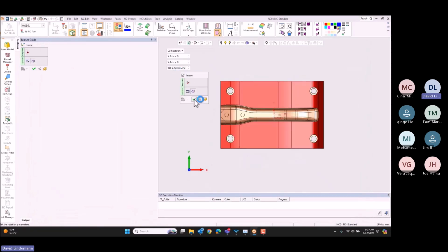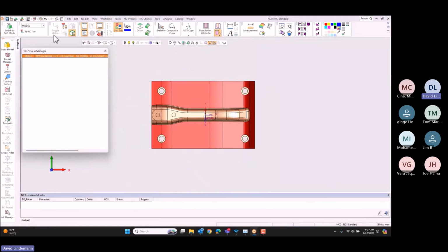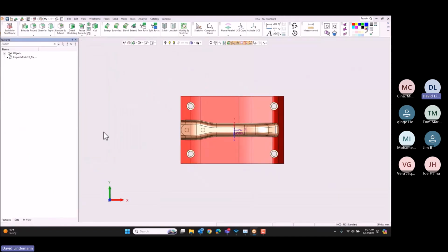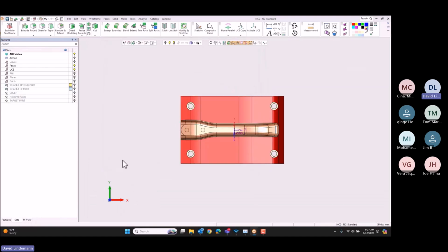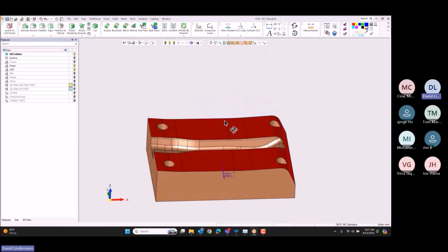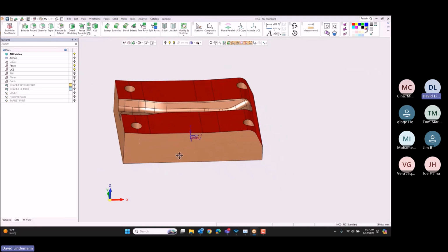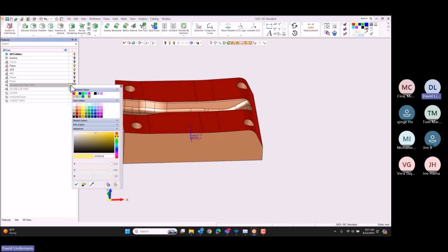Go ahead and set it up. I want to rotate that lengthwise on the X-axis of my machine. I had a few things I did before, like plugging those holes where I've got the socket head cap screws. I wanted to set up my different sets, and you can see the sets are already there. It's just a matter of telling it what particular parts of this insert I want on that set, and then picking it as appropriate.